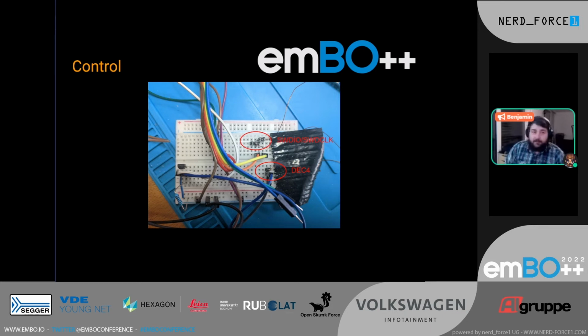I soldered it because I didn't have the correct adapter on hand to connect an external Segger. And I also couldn't use the internal one because, due to all the resets I was doing with the power offs, I somehow corrupted the firmware of the Segger every time I reset it, which meant I would need to reflash it, which slows down the process, and thousands of reflashes can't be good for it. So I just connected an external one and it works far better. The J-Link is connected via these wires, and it's a standard J-Link, nothing to see there. And the only component doing anything else other than cable management is a small transistor.